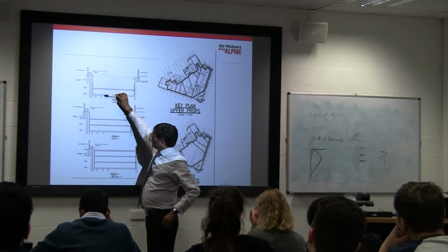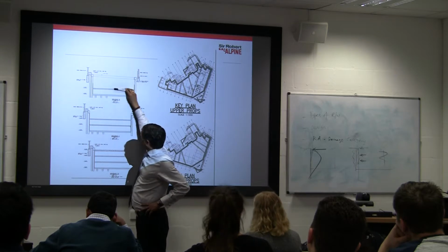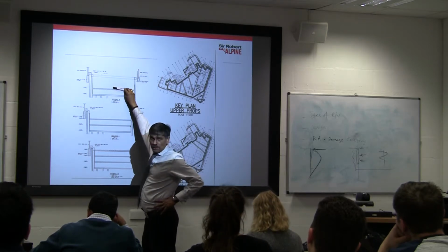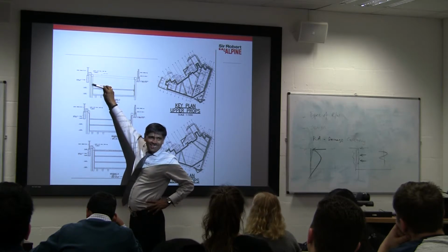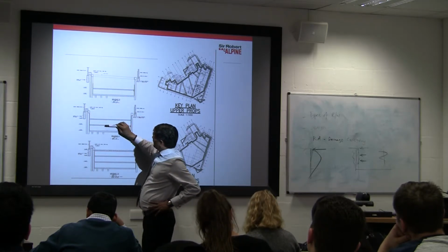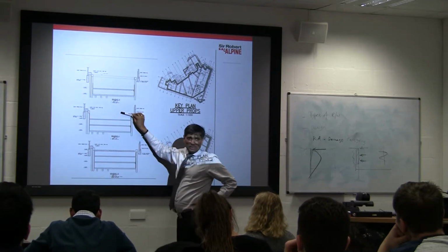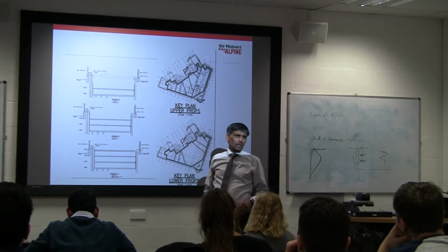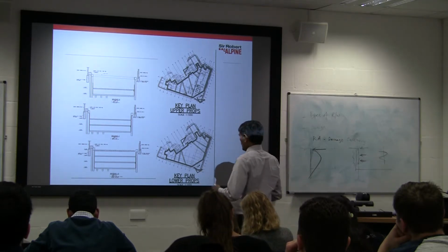So we build a slab at this level, then we are moving up, so we build a floor there, because that is one basement. So when you build that basement, you can see that prop is already gone. Yeah? And then we build the next one, you can see when you put that one, that prop is already removed. So you sequentially build every floor bottom up. So this is another sequence.